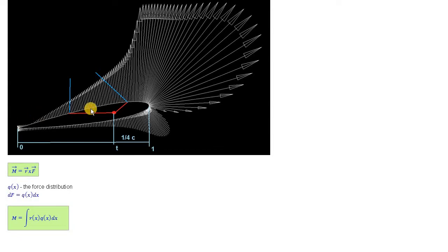Basically you have this vector going to each point of the airfoil, and at this point you calculate the projection of the distribution of force onto the normal to this vector, and build this for the whole surface. Pretty simple. But we will split this airfoil into two sections. It's easy to calculate, and you have more insight into what's going on. So we split this into two sections: one section before the point at which we measure momentum, and the second section up to this point.